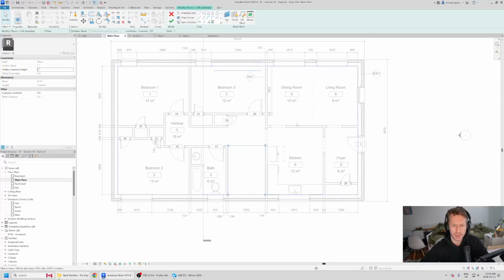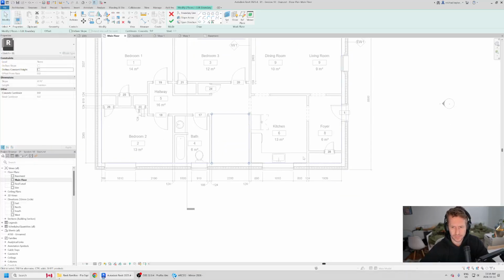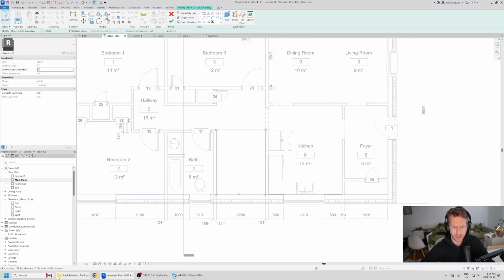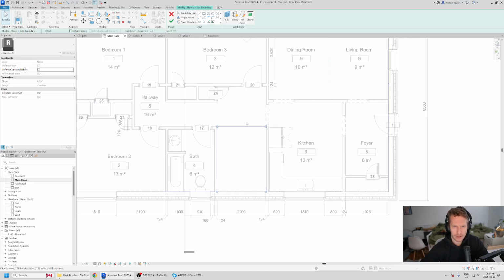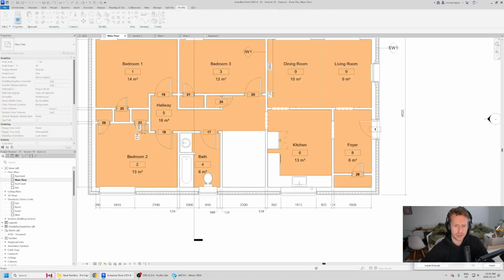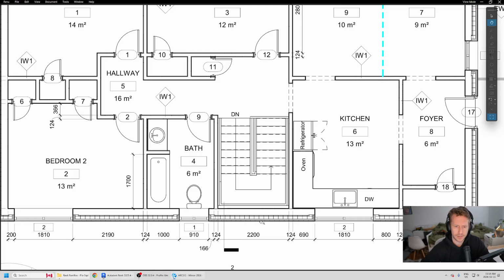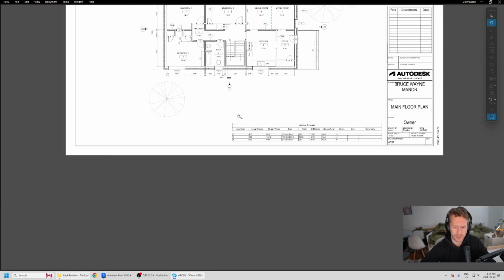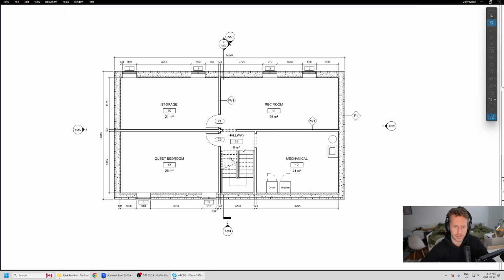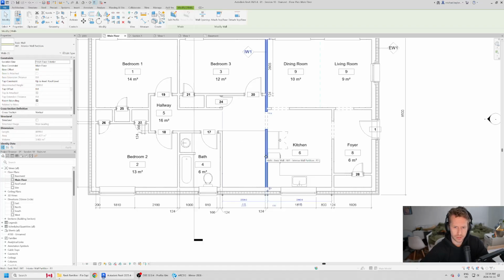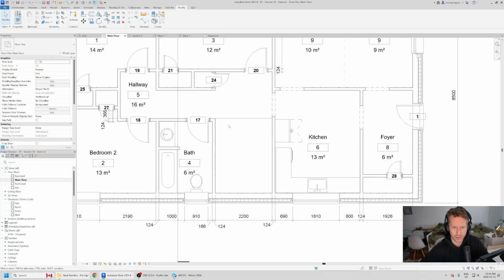So remember that this profile needs to be continuous. So we can't have any gaps in it. We can't have any overlaps. But when we actually go to draw our opening, the opening is going to sit here. And if I hit the little check mark here, we will see it says it can't keep the wall floor joint. Okay, unjoin elements. I have a feeling I know what's going to happen there, and that's okay. Probably going to need to, if I go to my next page here, whoops, I guess up, need to have those walls come down to grade or create some new walls here. So that's okay for now.